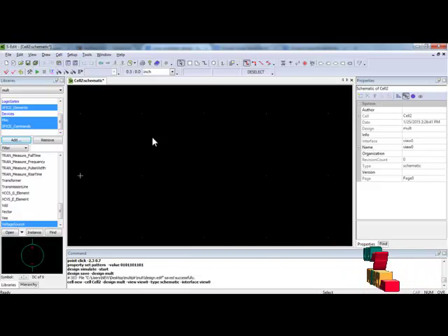Through T-Spice you can see the netlist available. In T-Spice, the components which you have used are listed as component code. That means you can see it program-wise, which is why the T-Spice code is called a netlist. You can run either from S-Edit or from T-Edit.